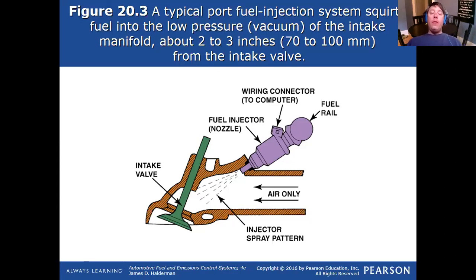And we call the most modern port fuel sequential port fuel. There's a few different kinds of port fuel systems out there. In the early days, the technology wasn't good enough that we could literally fire those injectors on a firing order. So they used a system called gang fire or batch fire. If you had a V8, for example, they would spray the even cylinders and then the odd cylinders, then the even cylinders and then the odd cylinders.